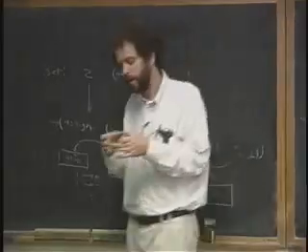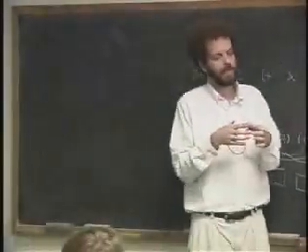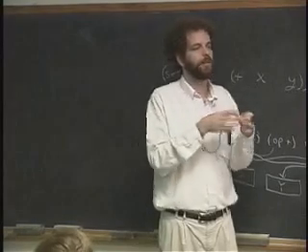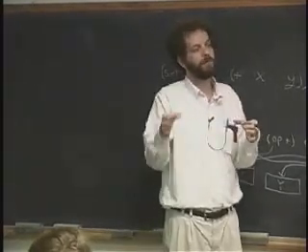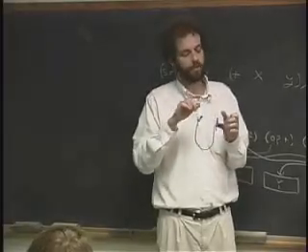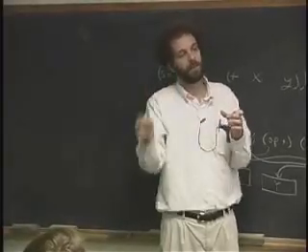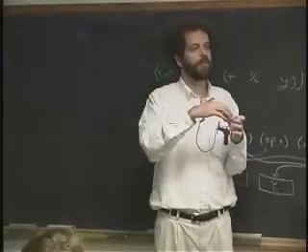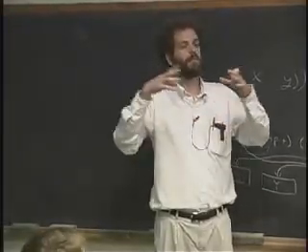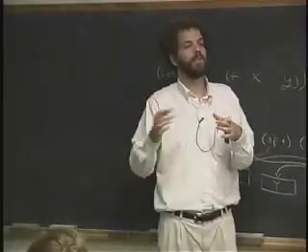So what that means is that past a certain size, the memory has to no longer be on the same computer chip as the arithmetic logic unit. It needs to be off chip, and the data needs to move back and forth. And as we'll see later on, moving that data off the chip and back onto the chip takes time. And thus that is another reason why the bigger the memory system is, the longer it takes to access it.